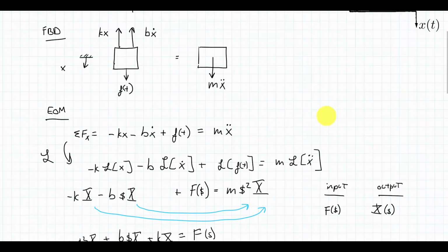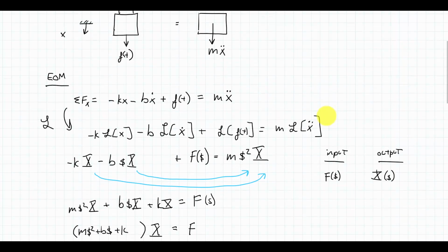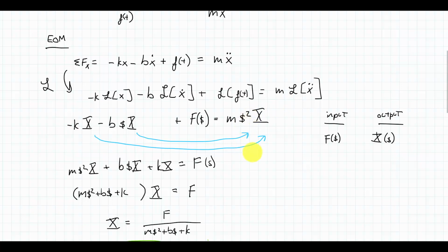It's a single equation of motion because we have only, again, this single degree of freedom. I want to go from the time domain into the frequency domain, so I took the Laplace transform of both sides. x is a function of time, as is f, so it is affected by the Laplace transform, but my constants m, b, k are not, so they can come outside of these Laplace transforms. I then do the Laplace transforms, noting that in this case I started at equilibrium, so my initial conditions were all 0, and that's why after the Laplace transform, we have this pretty simple line in the frequency domain, because those initial conditions all dropped out.